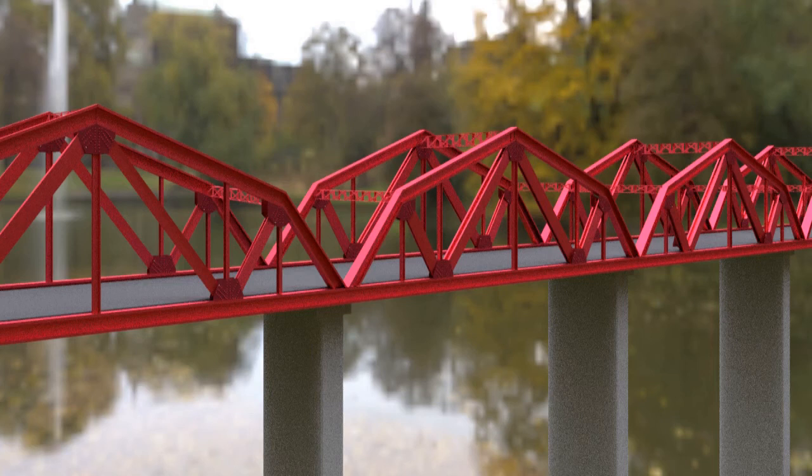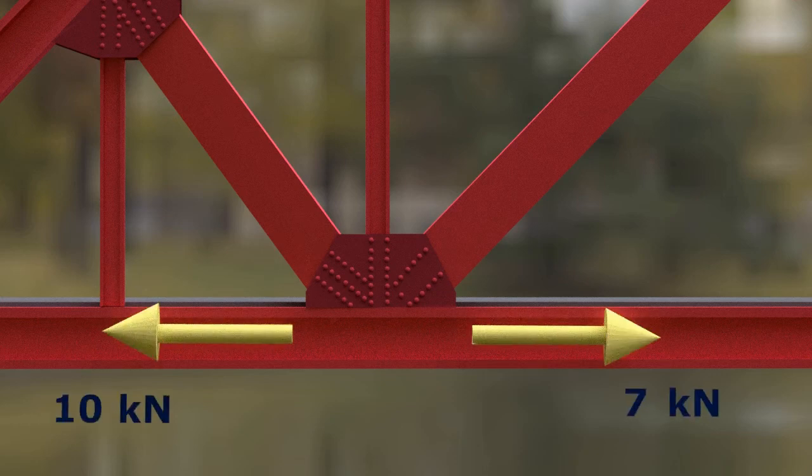So today we will see a problem on equilibrium of a component of the bridge truss. Forces are acting on the joints of all connecting members of truss. And we want to find out magnitude of some unknown forces on one particular joint. Now let's have a look at the given data. Two horizontal forces of 7 kN and 10 kN are acting on joint but are in opposite direction. 2 kN force is acting in vertically downward direction.